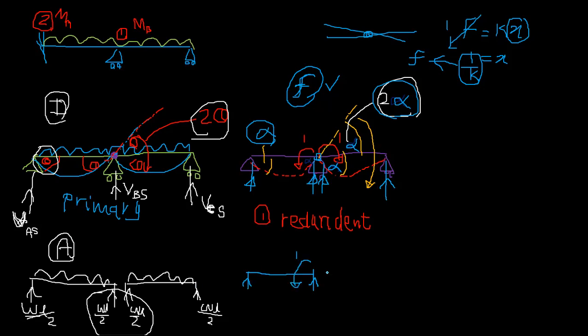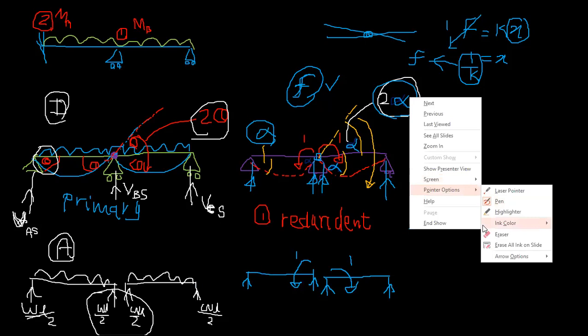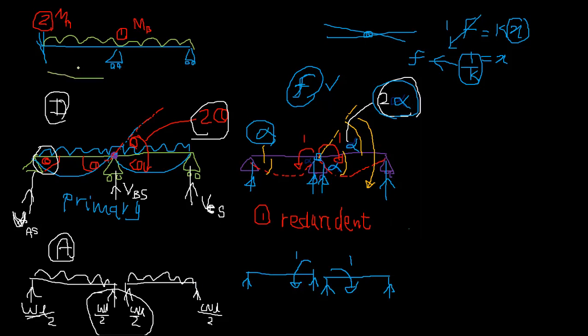It's just one bending moment, just unit bending moment. Okay. So your reaction would be, so this is L and this is L. So you can take bending moment about this point. 1 is equal to this force into L, right? So it would be 1 over L, right?